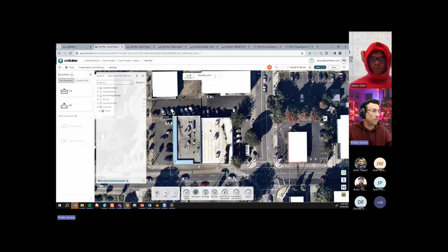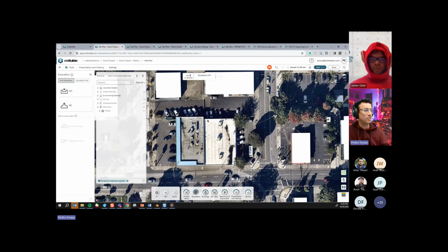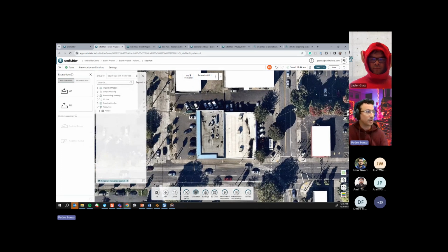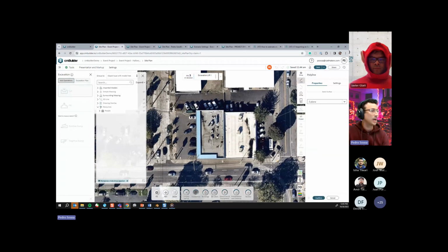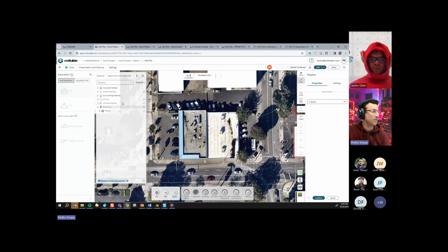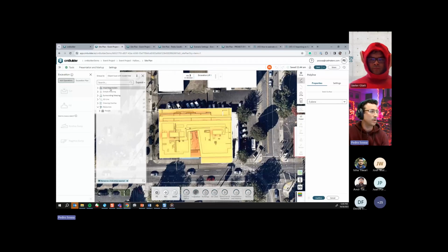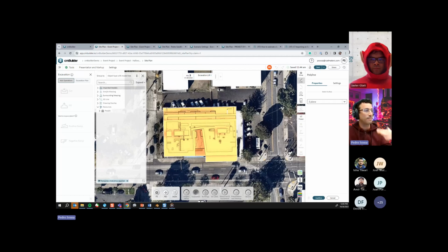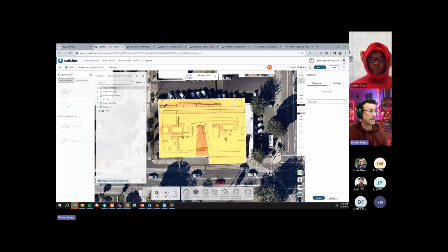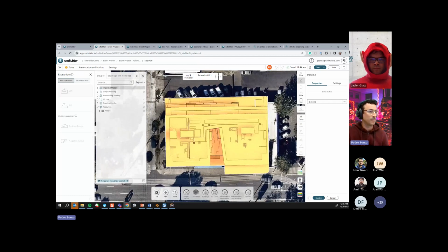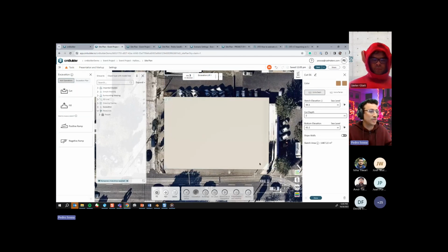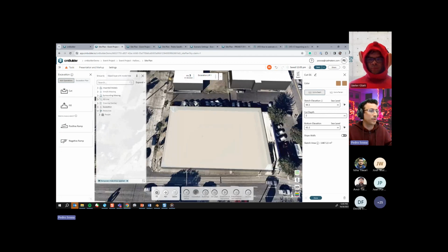Usually on your excavation stage, your building is not showing up on your screen, so you can click to create a cut. If you want to use your building as a reference, you can simply click on the imported models in the tree to bring that building back, and you can see exactly all the limits of that building. Let me quickly create one excavation rectangle. It's going to be super simple. And when I hit confirm, you're going to see that an excavation was created.